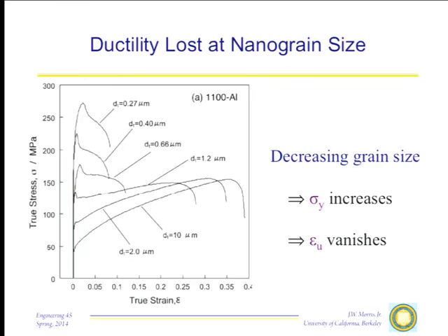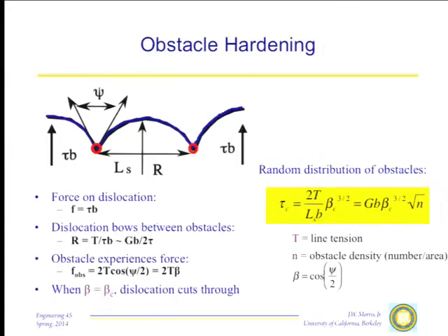Well, if you have a stress strain curve that looks like this, no problem. You've got plenty of cushion for that little kind of deformation to happen. If your stress strain curve looks like that, the game is over, because the minute you get any deformation at all, the part's going to break. So you really do need this kind of cushion, and it's designed into materials.